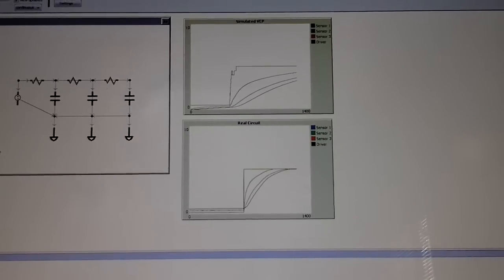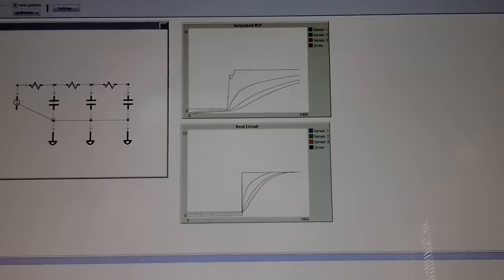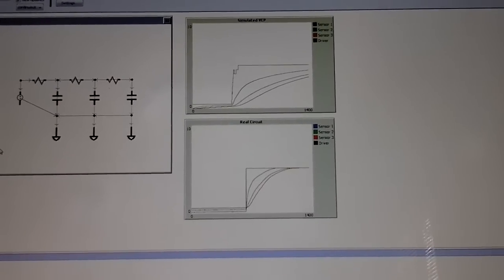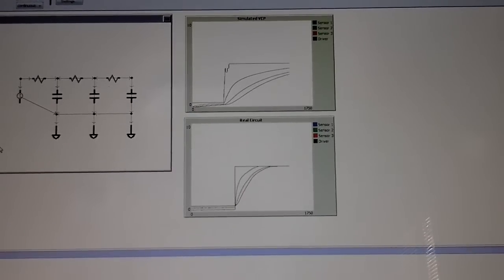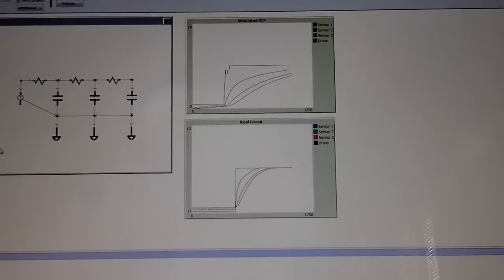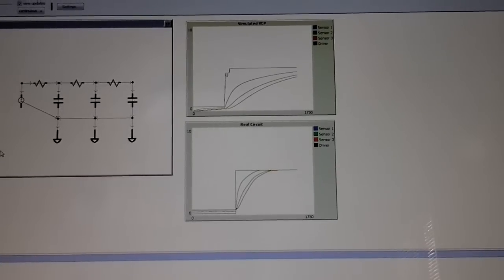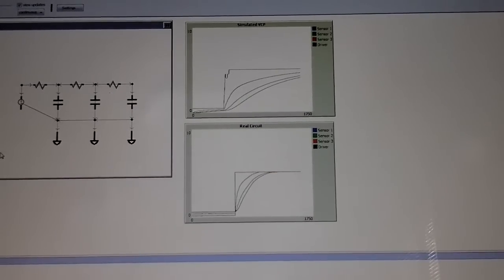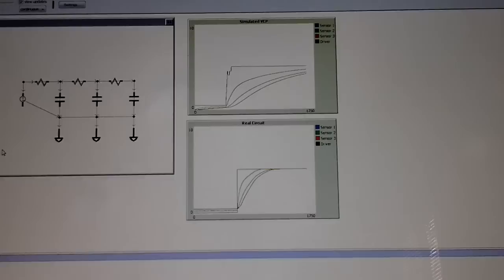The reason they go in this order is that as the voltage source dumps charge onto the first cap, its voltage increases. And as enough charge is accumulated on the first cap, it begins to both shift current from the voltage source onto the second cap and begin sharing some of its charge. The reason that there's a delay in this happening is that the resistor there limits the amount of current that can be shifted through without a high voltage on the first cap.